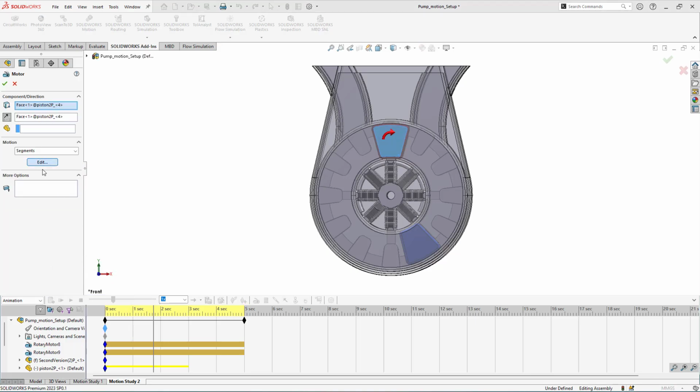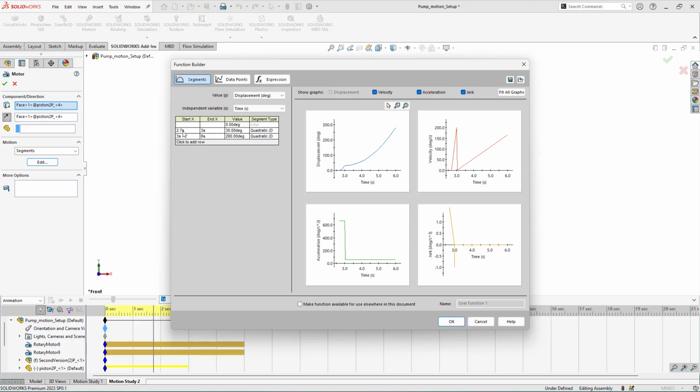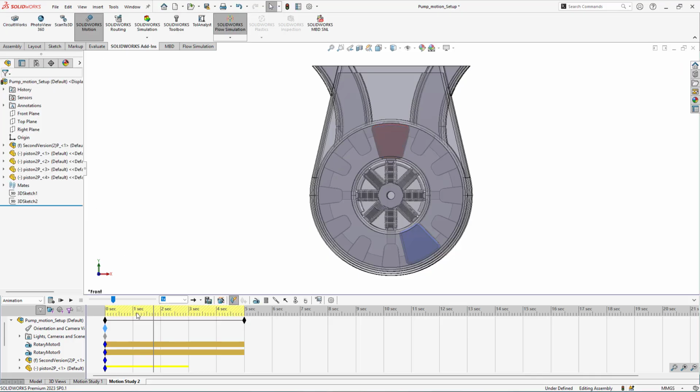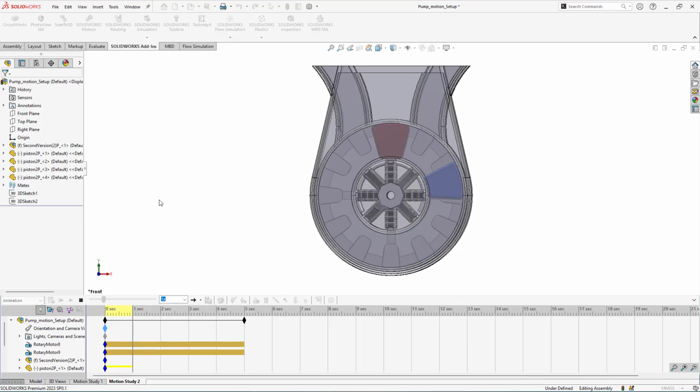Yeah. So now here, instead of 2.7, make it 2.6, so that I can avoid the interference. You can even make it 2.9. So exactly at 2.9 it should move, and then it should start from 2.9 itself. Let us see. Click OK, run it. So coming, oh, still it is interfering, right?